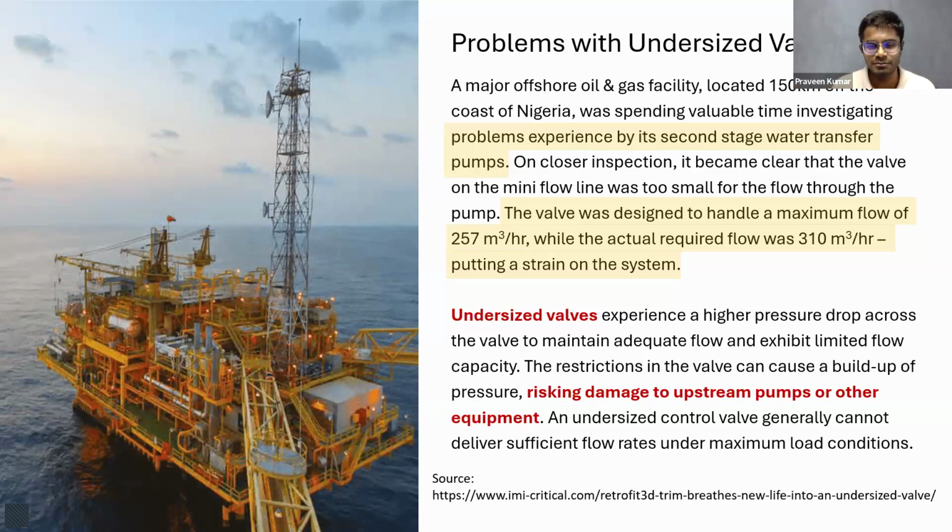Just take a minute and think about what would have caused this undersized valve in the first place. Either the sizing calculations might have gone wrong, or the data provided by the manufacturer might have had inaccuracies.